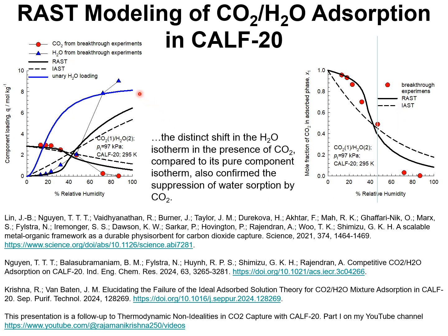I had also stressed the fact that the mixture adsorption data on which the analysis is based is obtained from breakthrough experiments that are not conducted under strict thermodynamic equilibrium conditions, and that explains why the water loadings at high relative humidities exceed those of the unary water loadings.